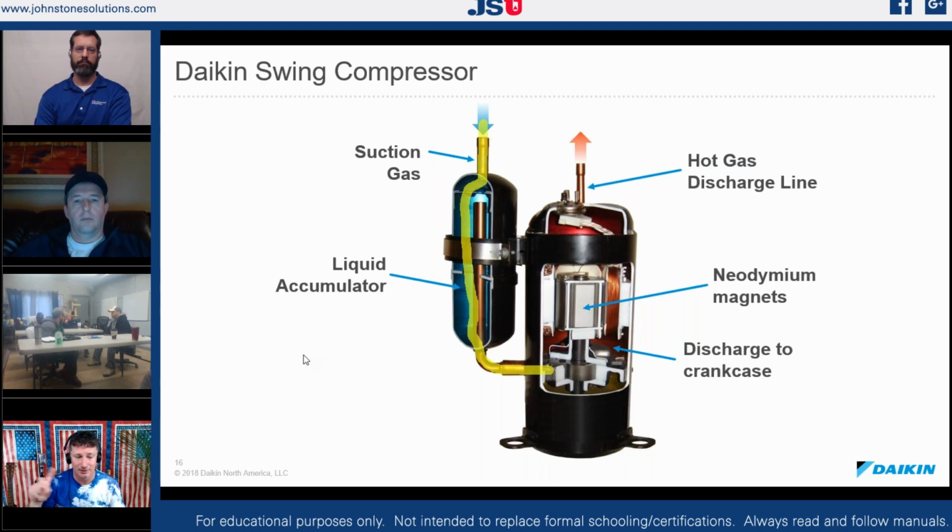Because I had to prove this correct. I had an installation, a contractor called me and said, hey, I just installed this brand new unit. I've got locked rotor right on the get-go. I was like, okay, I want to test something. Did you open the suction line or the liquid line first? He says, well, open suction line. I was like, okay. I explained this to him. I said, all right, so we now have no oil in our bearing.